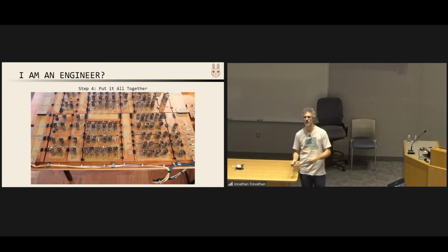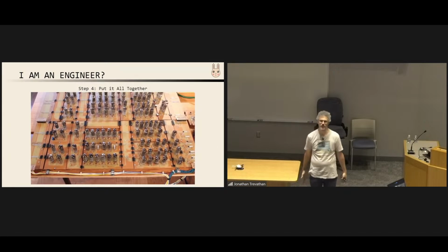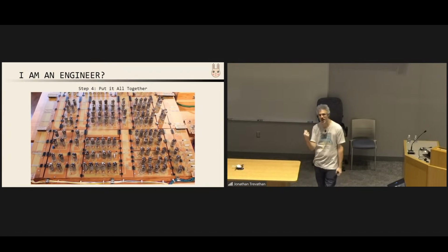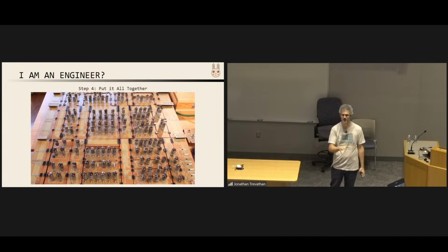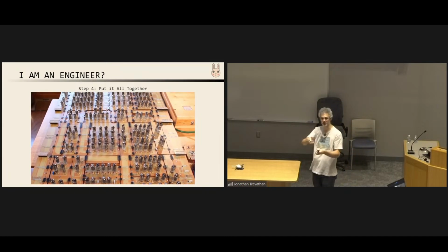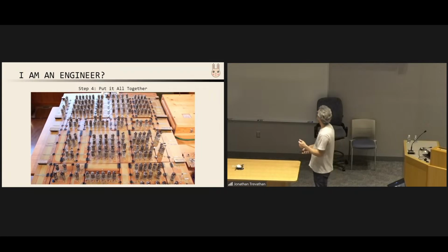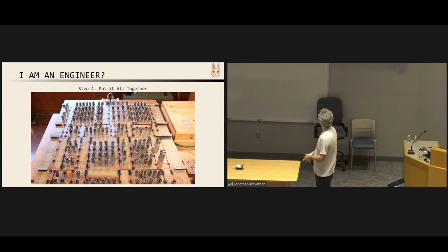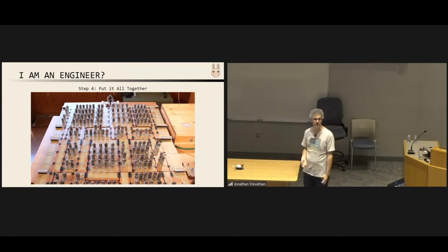I mean, you can't really see much there. So here's an actual video of what it looks like. The tubes are not directly soldered to the PCBs, don't worry. I actually have 1 millimeter pin headers in there, so the tubes are in sockets that I built from scratch. And there we go, all bolted together. It actually worked too, which is insane. It didn't even need that many bodge wires.